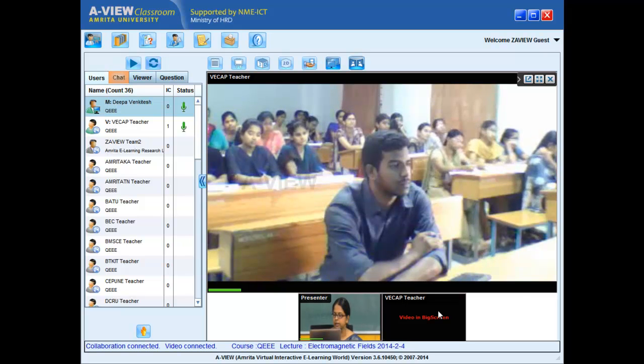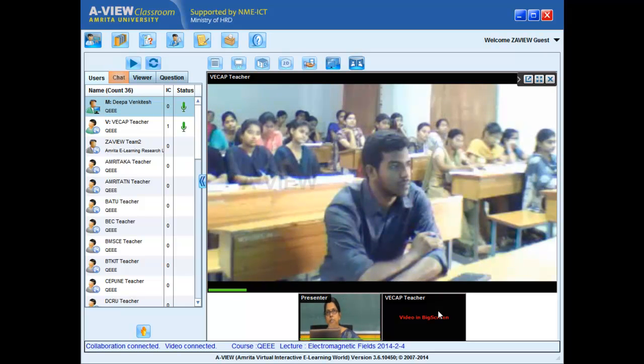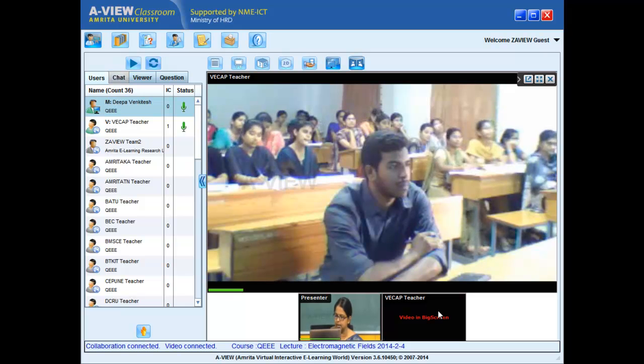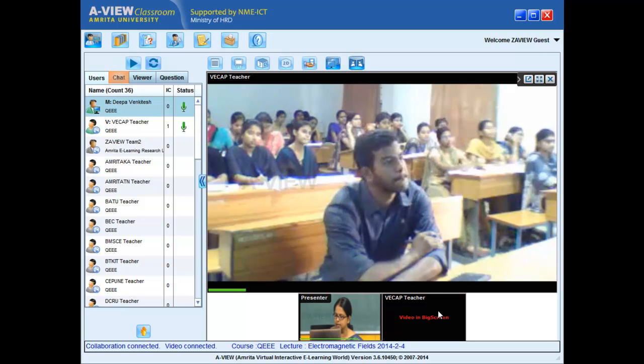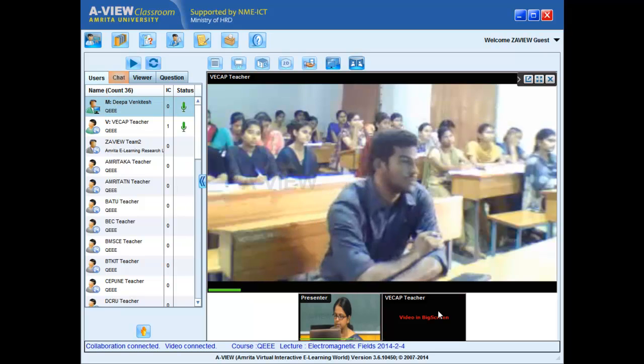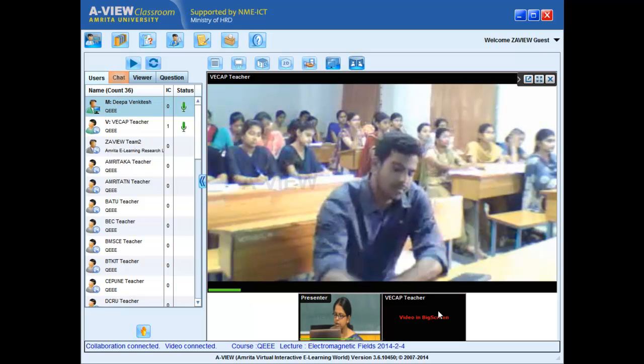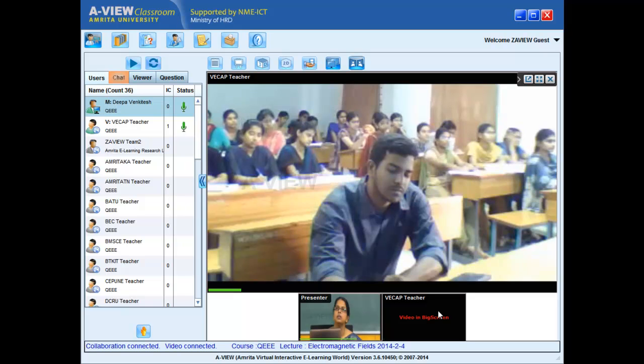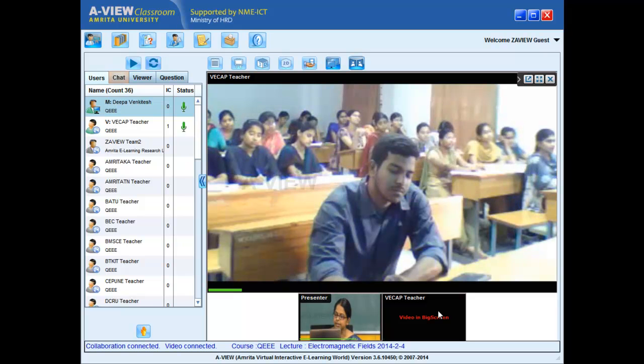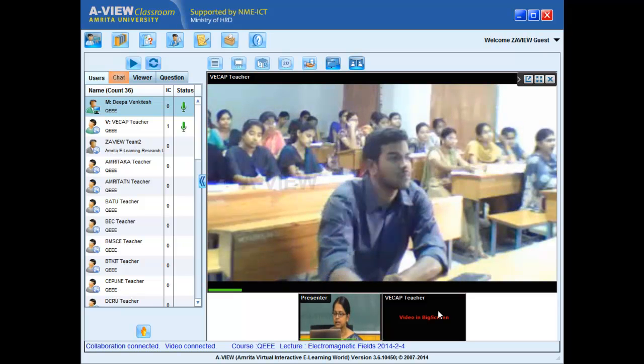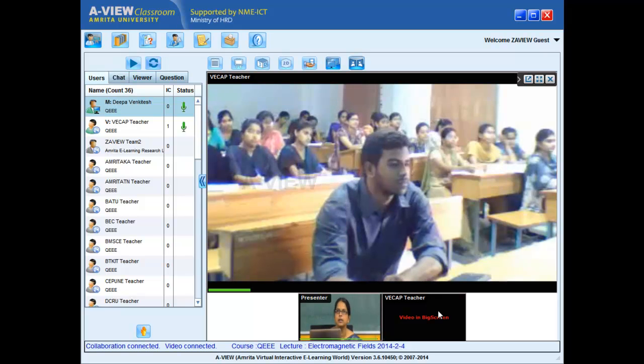Here we are saying that there is no more a V naught; this V naught is actually changing as a function of z. So let's figure out how it changes as a function of z. Now remember, this part is time independent. That's what the phasor representation does. It isolates the time dependent part from the time independent part.